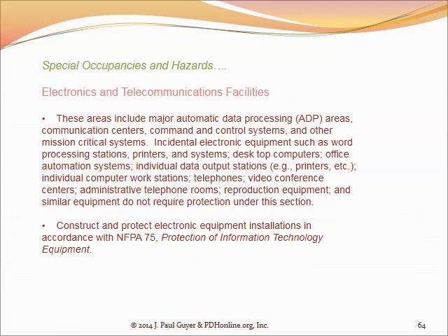And so you could have situations where a simple little fire might start in a wastebasket or something like that, a minor little fire, but it would trigger the fire sprinklers to open and dump large amounts of water, potentially on the data processing equipment and on the computers, and of course probably irreparably damage the equipment and cause the loss of data.